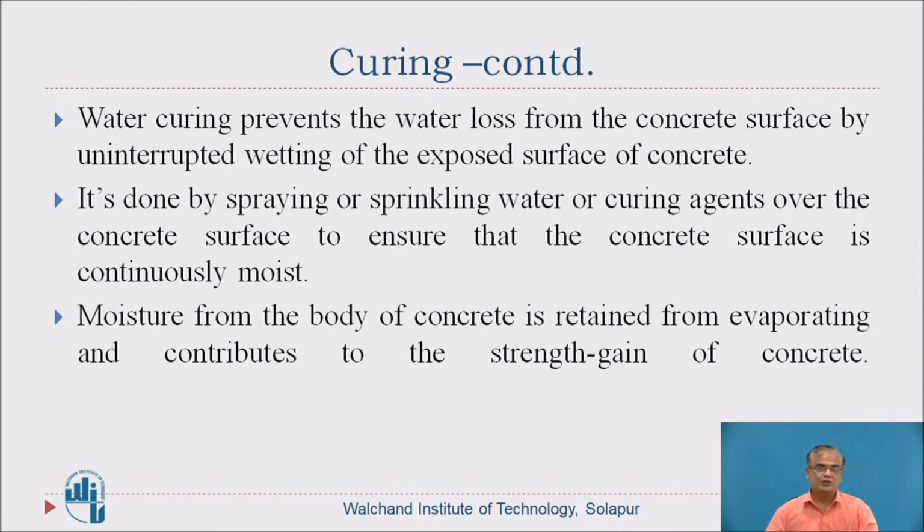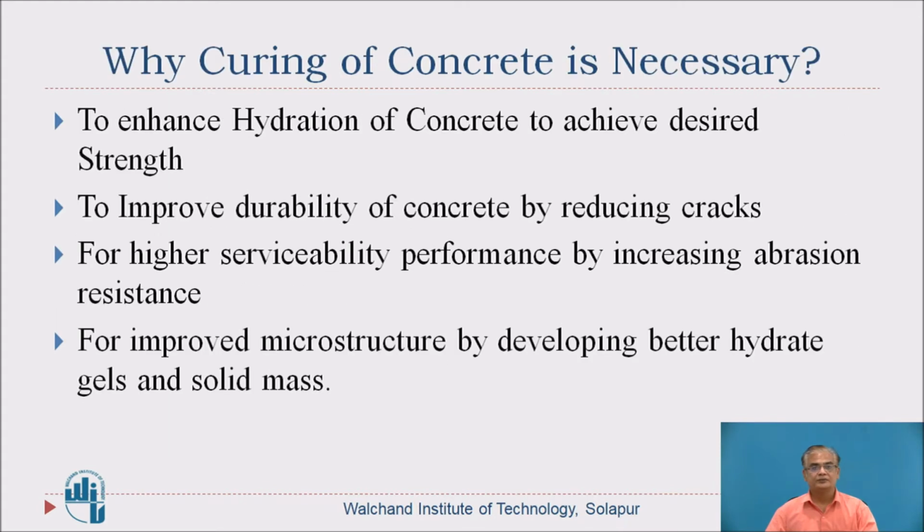So when this moisture is prevented from evaporation, right, what will happen? The hydration of cement will be complete and concrete will gain strength out of it. So once again, why is curing of concrete necessary?